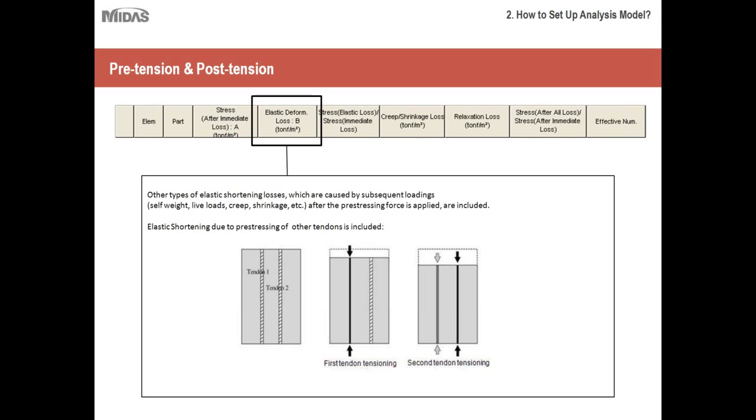So you must account for these types of elastic deformation, because in splice girder bridges, this is a phenomenon that will definitely occur as you are post-tensioning a prestressed section, and you have to account for all these other effects.